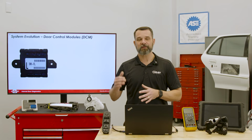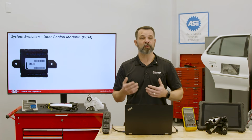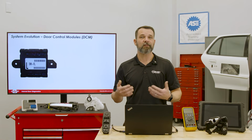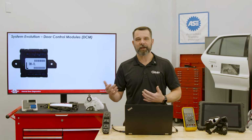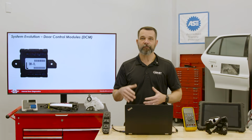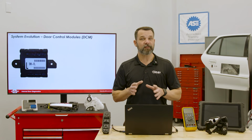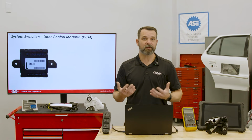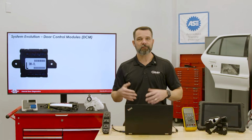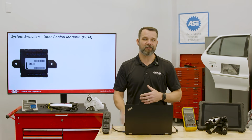Now, the DCM has direct control over several components inside the door, such as the power window motors, door lock actuators, mirror adjustment motors if you've got them on the vehicle, courtesy lights, and even puddle lamps, and then local switches like the passenger window switch. It also monitors a lot of position sensors, current draw, and limit inputs for safety features like pinch protection on the power windows. And believe it or not, DCMs fail more often than people might expect, mostly because of their harsh environment. You've got heat, you've got vibration, moisture finding its way inside the door, and so we have some pretty common failures on these as well.